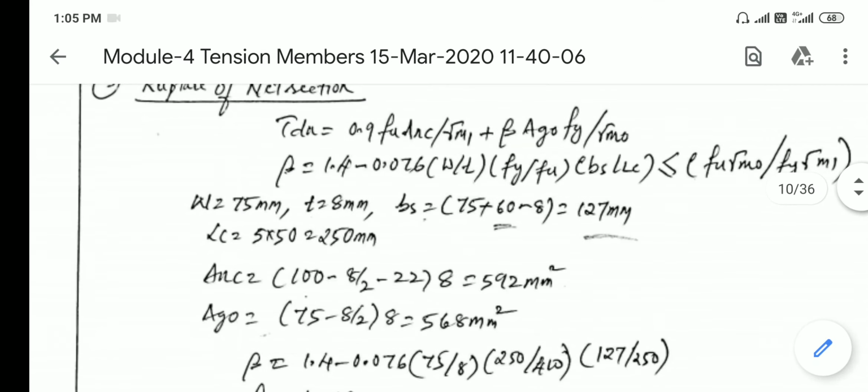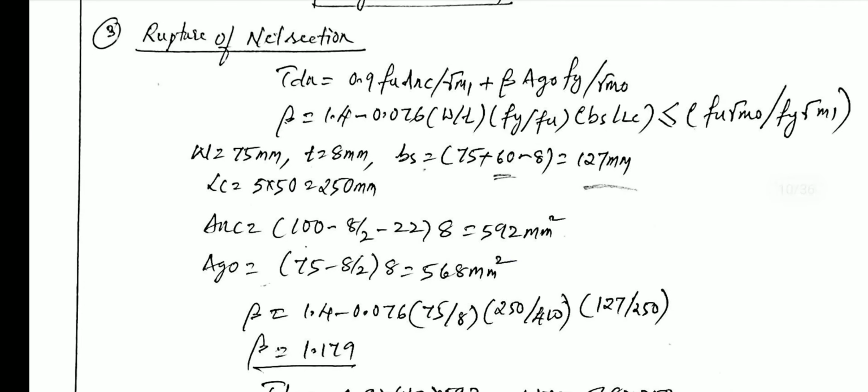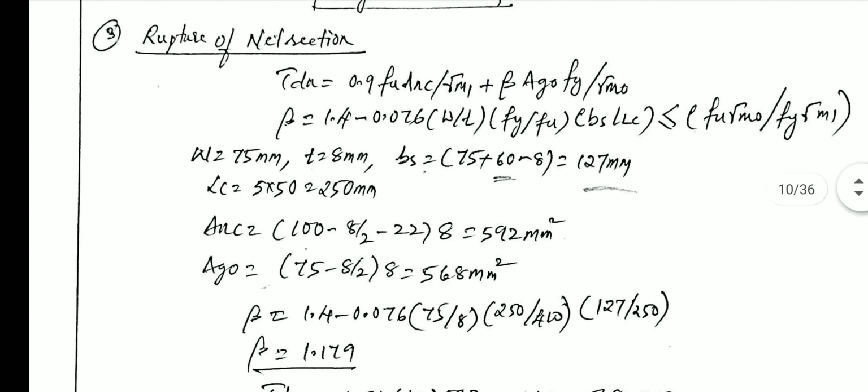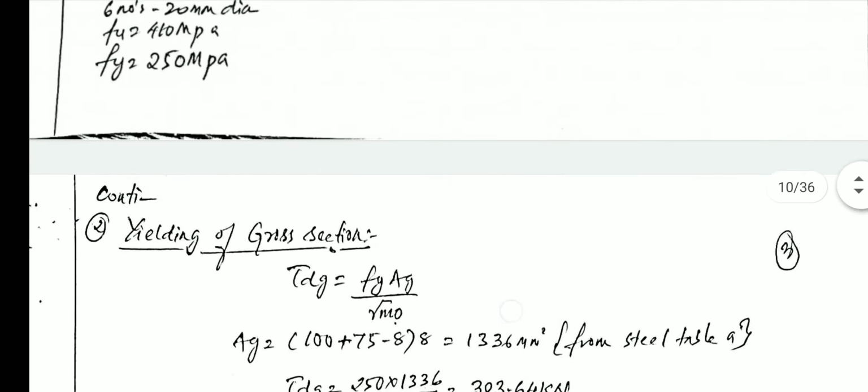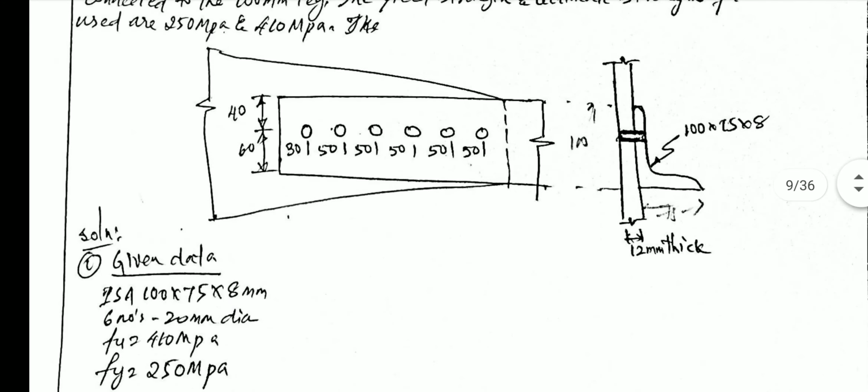According to my steel table, the page number is 168. It may differ from your steel table. Now come to the point here. Once you get 75, how you get 68, we already explained. So minus 8, you get 127, and this formula is given in the code book, page number 33. Now let's see Lc. Lc means what happened? Length between the holes.